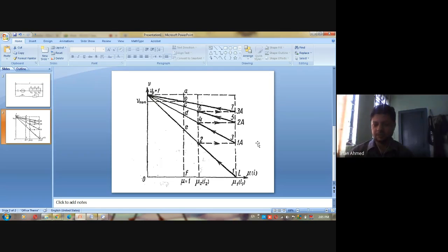The insulation of the armature winding. But in case of DC motors, even more important than that is how much current your commutator can allow to flow. Is this clear? Because at your commutators, sparking is possible if a very high current flows. So this current I1 is decided by the commutation circuit. Normally this current will be 2 to 2.5 times the rated current.